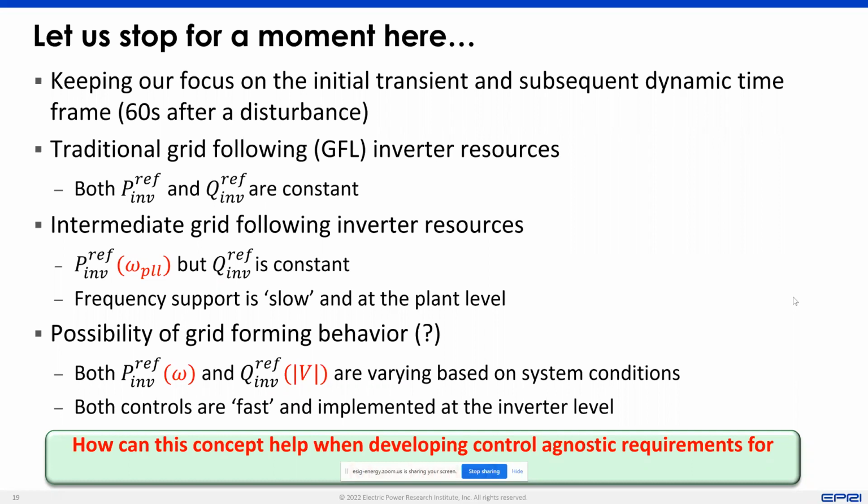So if you have, let's say, a series FACTS device, a UPFC or an IPFC, or if you have a phase shifter, which won't work in the time frame of a transient, it's more of a slower steady state. But if you have a FACTS device in the network which can change the phase angle properties of the network, there are certain instances where the frequency wouldn't necessarily drop.